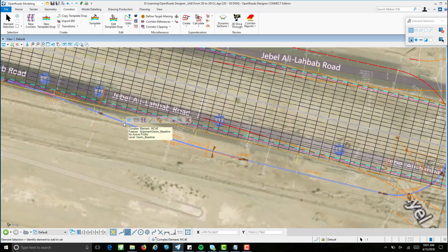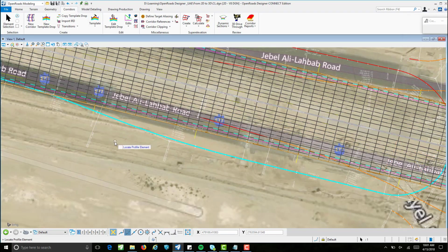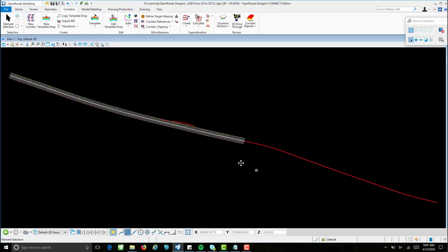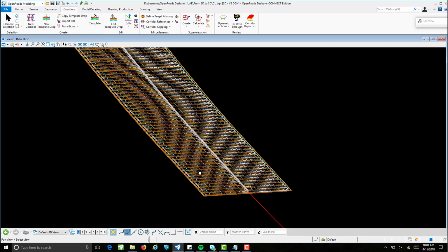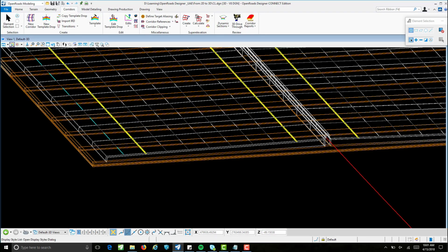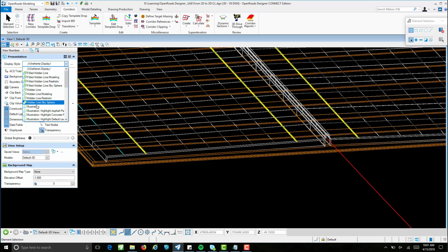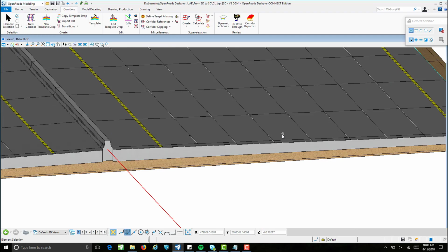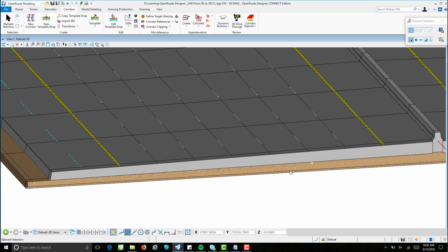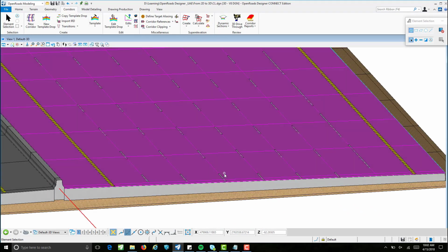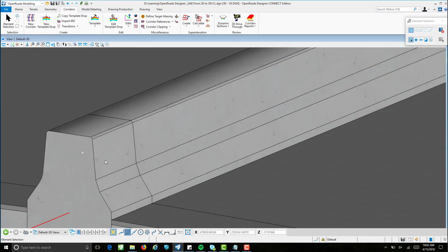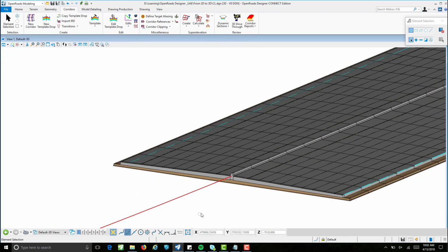So you start always in 2D. You can also do the other one if you want, but let's go to the 3D, and you see a nice 3D model also with the pavement markings. You can increase the brightness. So now you see the barrier, which are according to the standards, and the pavement markings. So everything is there, and it's a solid based model. So these were the steps from 2D to 3D.